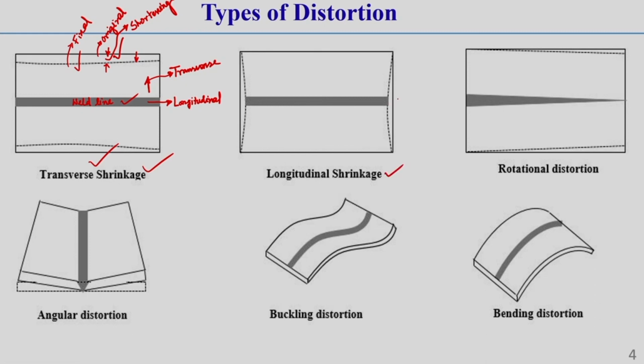that means along the direction of the line of welding, which is generally termed as the longitudinal direction, which I have already told earlier. So, these types of longitudinal shrinkage can also occur due to shrinkage of the weld material, correct? Because once the weld material solidifies, it creates a huge shrinkage force, or I am telling that its volume generally decreases. Due to this decrease of volume, there occurs a huge shrinkage force. Due to this huge shrinkage force, there can be a shortening of the longitudinal length. So, that is called longitudinal shrinkage.